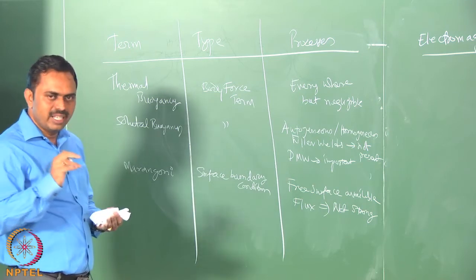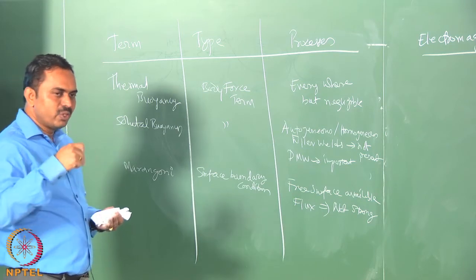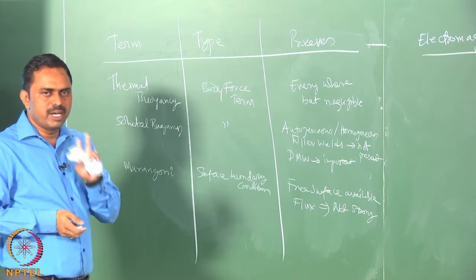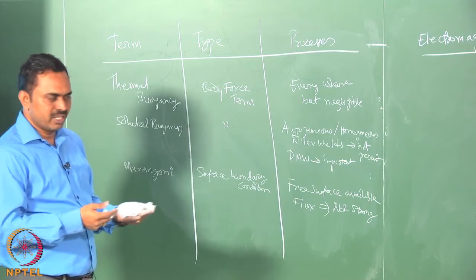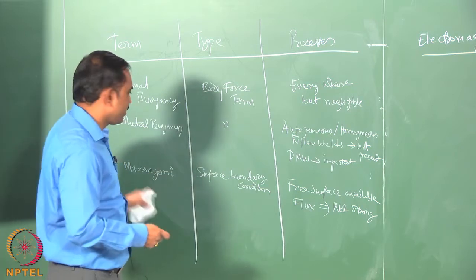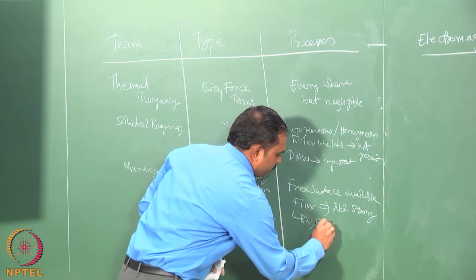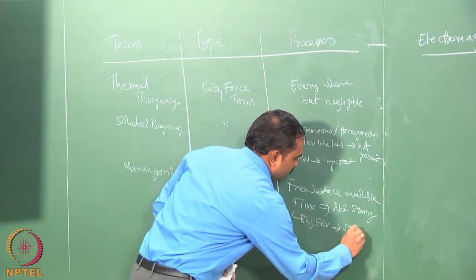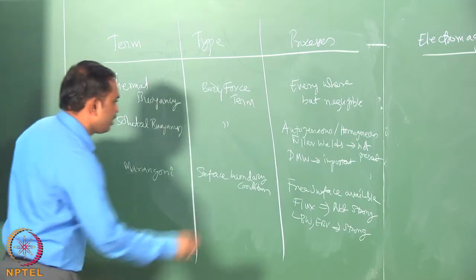For example, in laser welding and electron beam welding, the peak temperature is very high, and as you go a small distance in a small melt pool, the temperature drastically comes down to the fusion zone temperature, which is the melting point temperature. So, you basically have these effects very strong in LBW or EBW, simply because the gradients are strong. Okay.